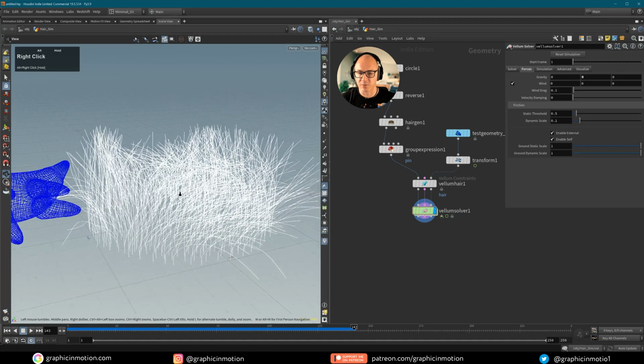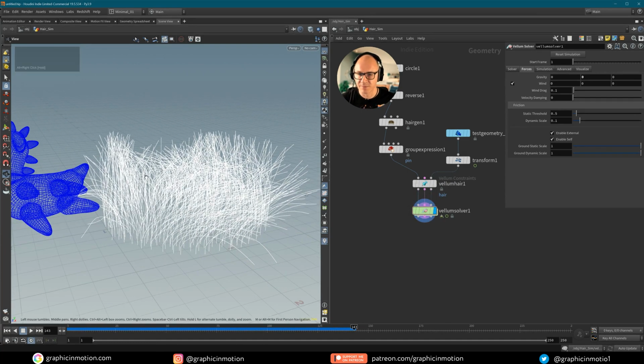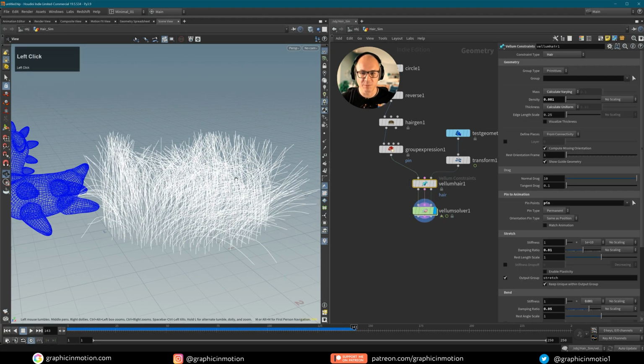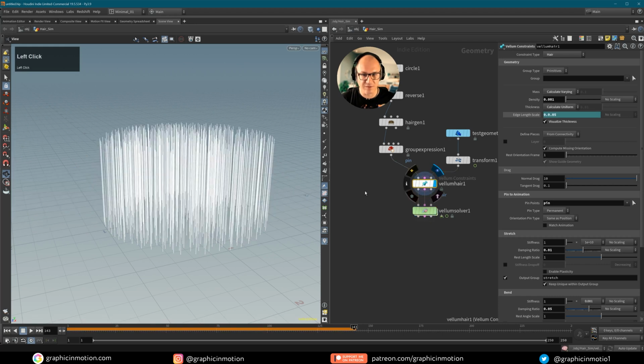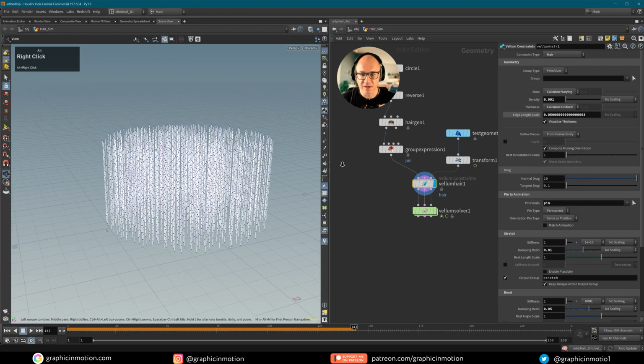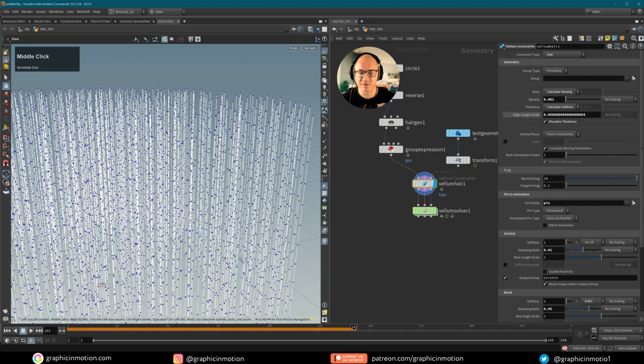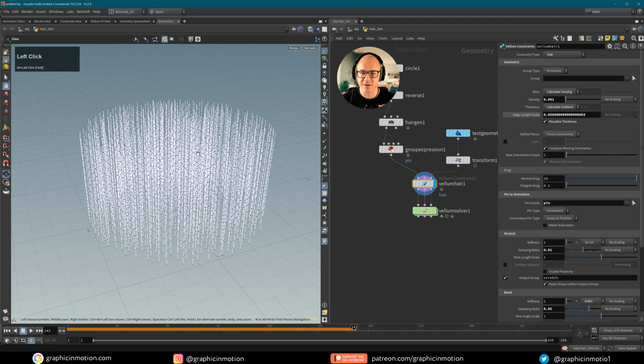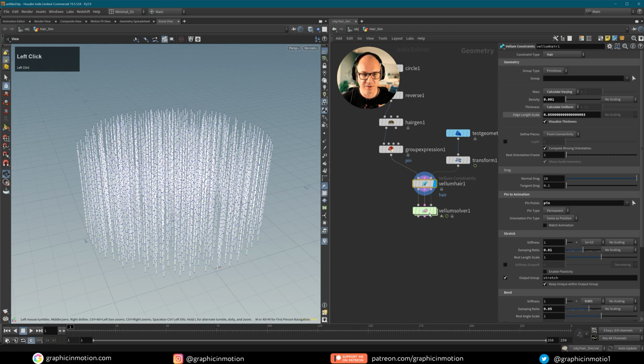And yeah, one more thing before I save this to disk. There is a problem that you can run into if you are working with very thin hair. So if you want to simulate hair that are really thin, for example, something like 0.05, and if we take a look here at these, oops, I made a mistake, 0.05. Let's delete the channels. You see these spheres now, they are quite thin. They are still not that thin as real hair, but they are way thinner. And if you want to simulate these kind of collisions, sometimes you run into problems.